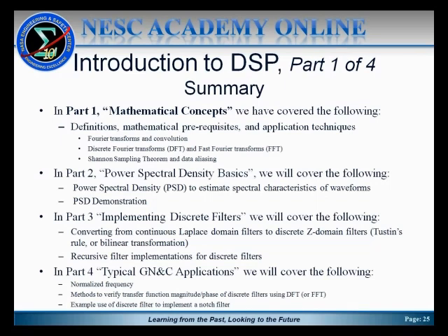In part 3, entitled Implementing Discrete Filters, we'll see how we implement these discrete Fourier transform concepts, and convert filters from the Laplace domain to discrete Z-domain filters using Tustin's rule or bilinear transformations. We'll also show how to implement recursive filters to implement these discrete filters.